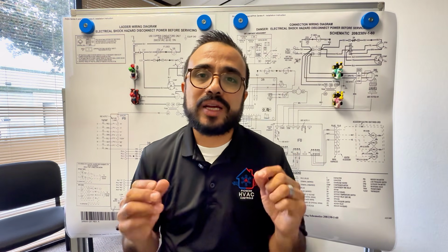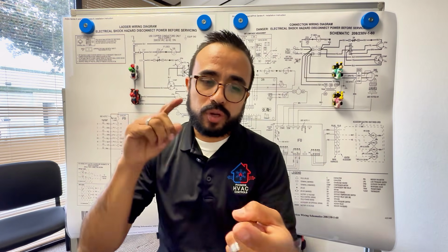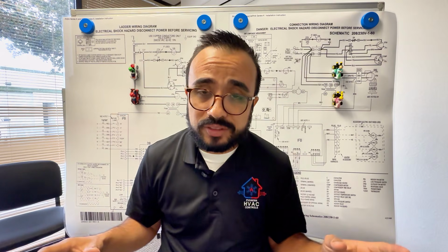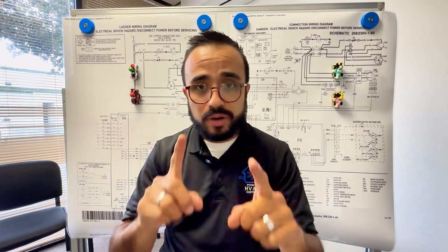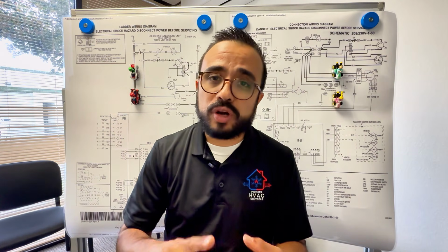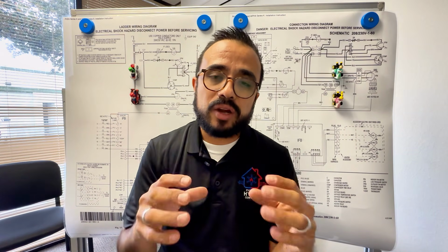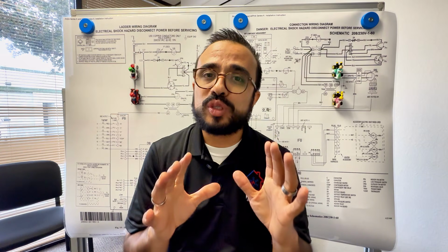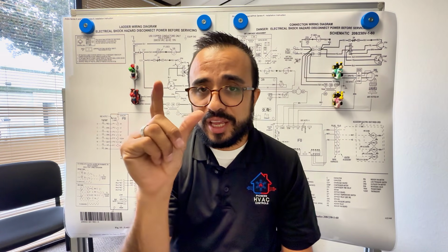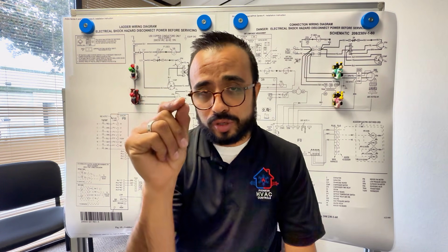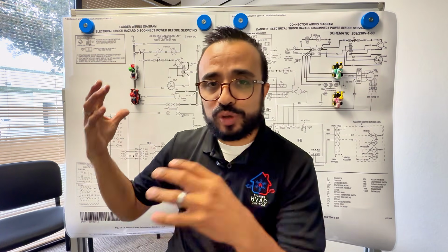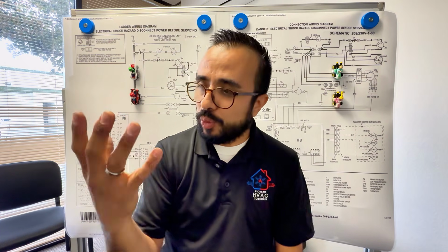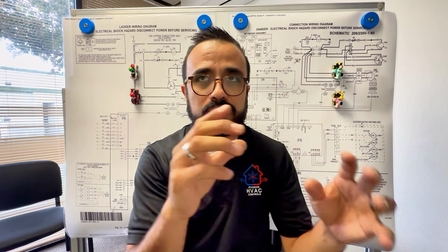But really, when it comes to schematics, when we're working with conventional air conditioning systems, gas furnaces, heat pumps, not a VRF, not an inverter, not a mini split, a conventional air conditioning system, all we're doing literally is this: is the bridge open or closed? Whenever you go to a schematic, go with your hand and see, okay, right here, is the bridge open or closed?